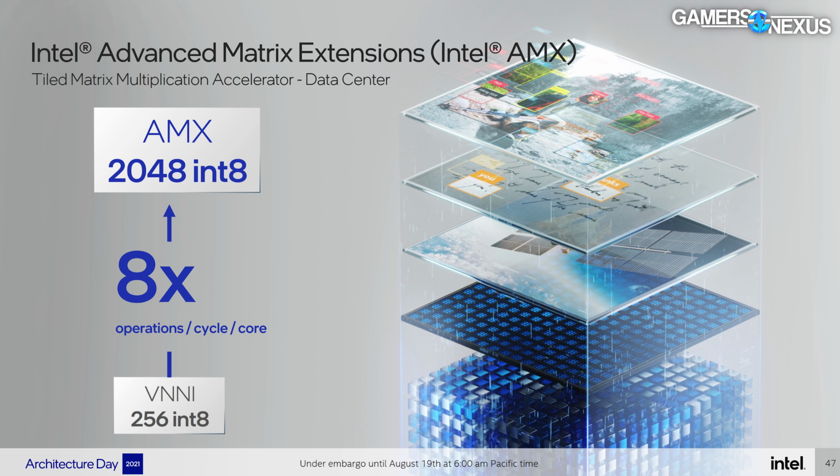In the vector execution unit, the P-Cores get a benefit that seems to be designed for the server and data center space, and that's AMX. There's new dedicated hardware and ISA for AI that's targeted at deep learning inference and training performance. Advanced matrix extensions, or AMX, enable the core to accelerate tiled matrix multiplications. Intel suggests that with AMX, the new cores can perform 8 times more int 8 operations per cycle than their existing cores, which, as we understand it, use VNNI, and that would be 16 times more than Zen 3, although obviously now you're getting completely cross-architecture, so there's a lot of other stuff to consider too.